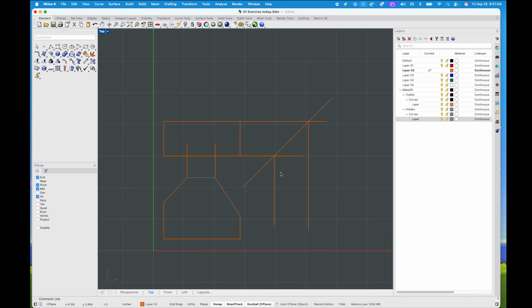I'm going to go ahead and extrude curve again. I'm going to give it about 1 inch. And now I actually want to chop away from this item. So I can use something called wire cut, and that's kind of the most advanced I'll give you for today because I do think it's a lot of fun to use. In fact, I'll just draw some lines over this portion right here, my front view.